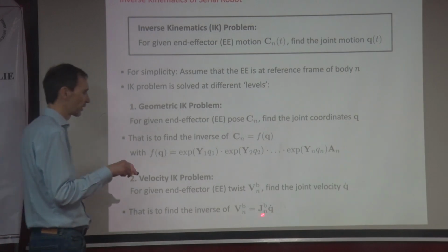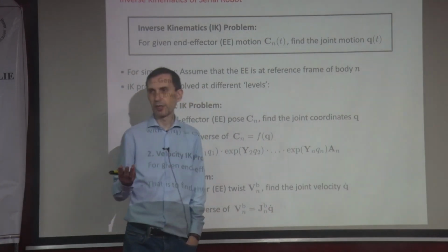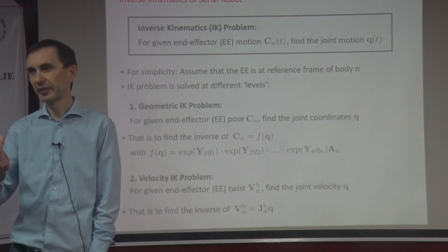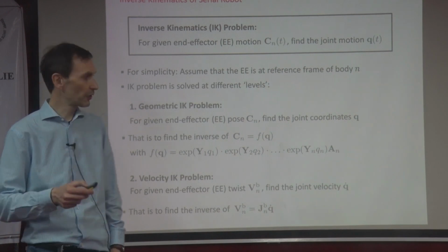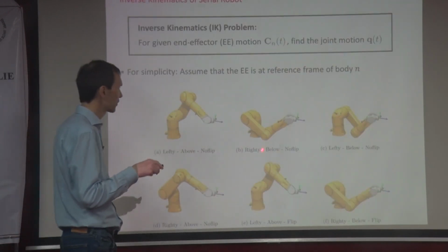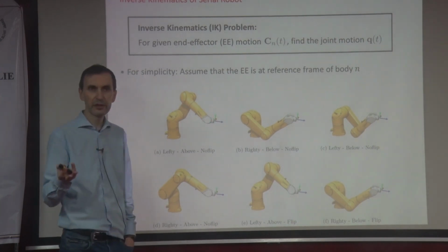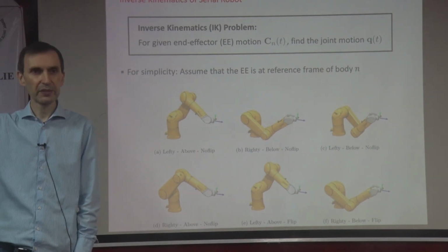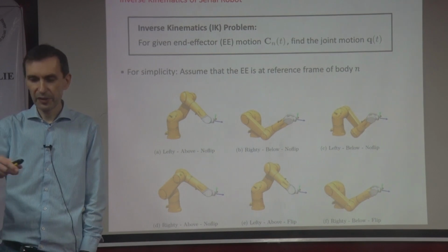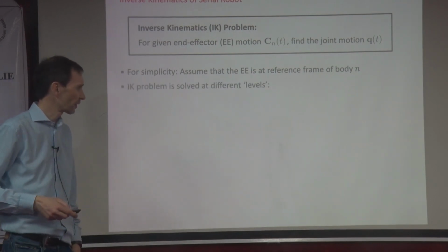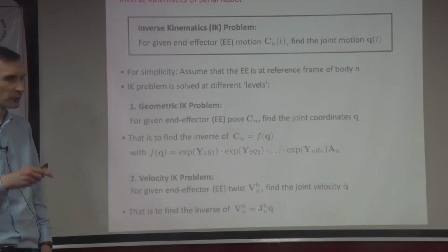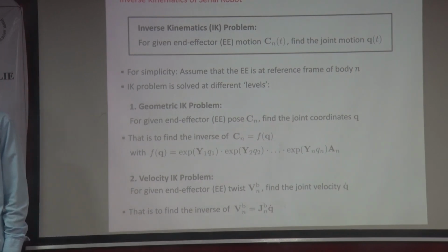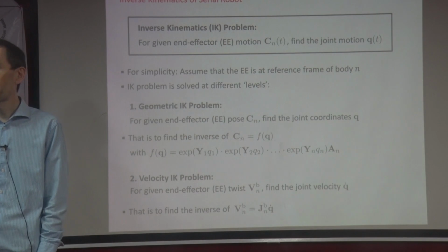What kind of robot do we have kinematically if it's non-square? So we have a redundant robot, they call it, right? For example, we have 6 joints, but let's say we have 7, then we have a redundant robot, because we have 6 output coordinates. The end effector has 6 coordinates, and we have 7 inputs. This came up in the area of human robot interaction. They started using them for whatever reason, and they call it an anthropomorphic arm.